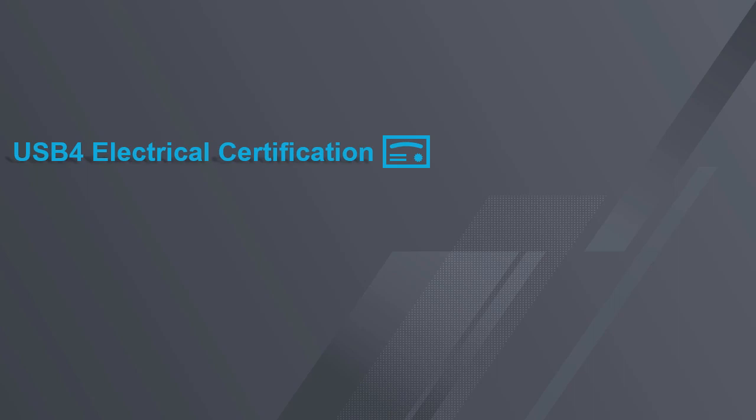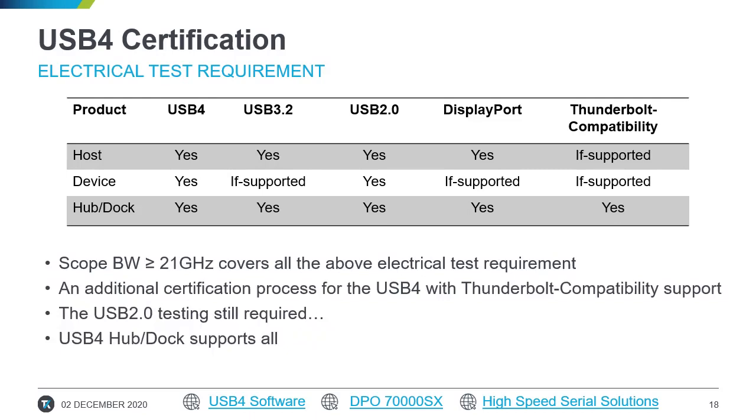Let's understand the USB4 electrical certification requirements. Here are the USB4 electrical certification test requirements, and they vary depending on the product type. If we are designing a host, we need to perform USB4 electrical, USB 3.2 electrical, USB 2.0 electrical, DisplayPort 1.4 or 1.2 depending on what you are implementing, and then Thunderbolt 3 compatibility mode. If it is supported, that electrical testing still needs to be performed.